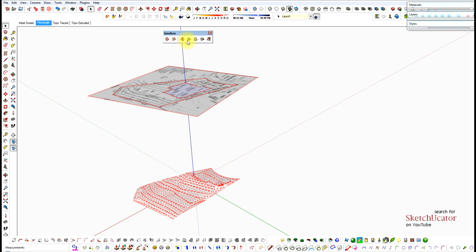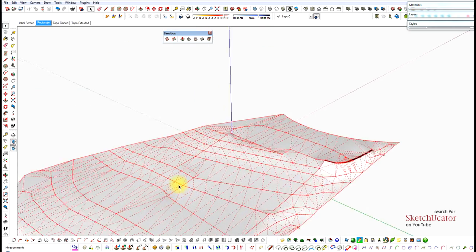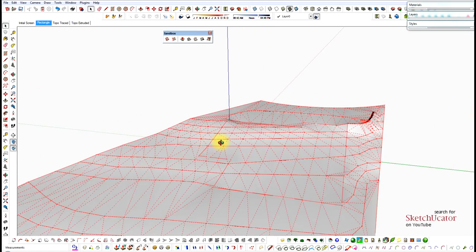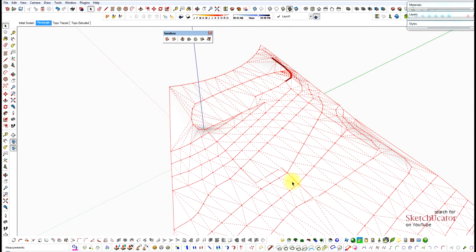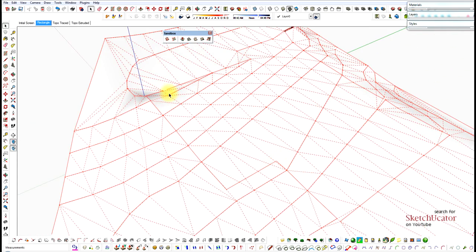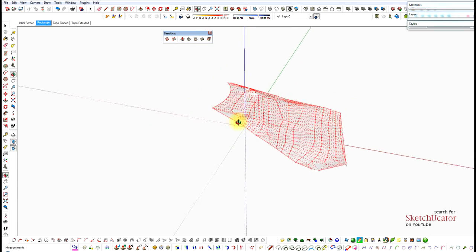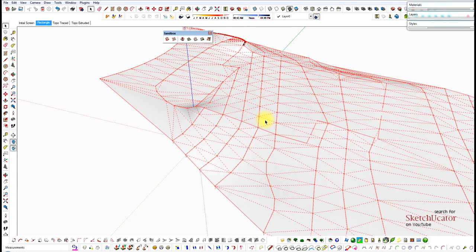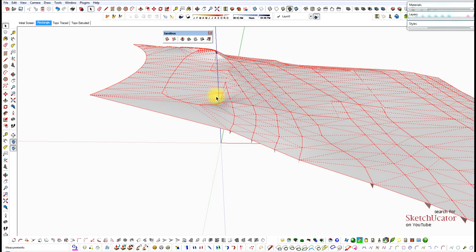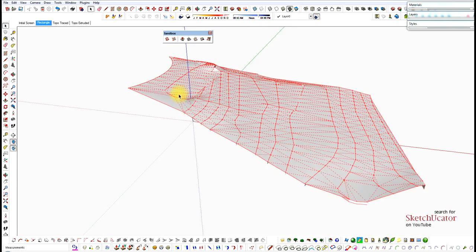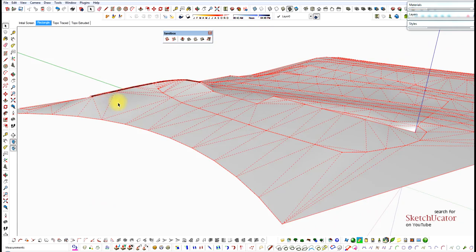With another sandbox tool here called Drape, I can select that, drop it on here, and you will see how I've transferred these lines, the information for that house, onto the site. So I now have a footprint, if you will, for that information. It's not really too difficult. You can do that with driveways or sidewalks or really any kind of other element that you may have.